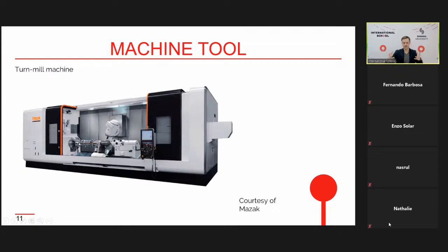Of course, it's a static picture, so we cannot see rotation here. But this is mostly a turning machine tool, so the workpiece rotates to form rotational surfaces. This part is also a clamping device to hold our long workpiece from the right side. And here we can see the part of the machine tool in which the tool holder is mounted. The tool holder is rather small here, but we can see this black tool holder, and the tool assembly ends with a cutting tool.